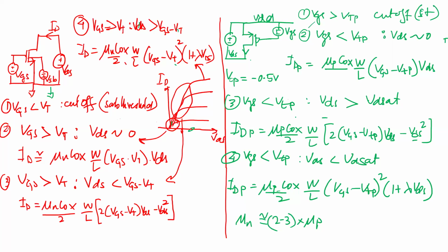Yeah, so the question is for audio devices, why do you use PMOS? You remember yesterday we did a common source amplifier, where you had NMOS with a current source. The low frequency noise is dominated by that first device. Okay, and that low frequency noise comes from, you remember when we did the VT derivation, we said there's a metal, there's an oxide, then you have silicon, right? And then in the last step of the VT derivation, we said the charges in the oxide are not zero. There are always some impurities trapped inside it. And those impurities are actually mostly in the interface.